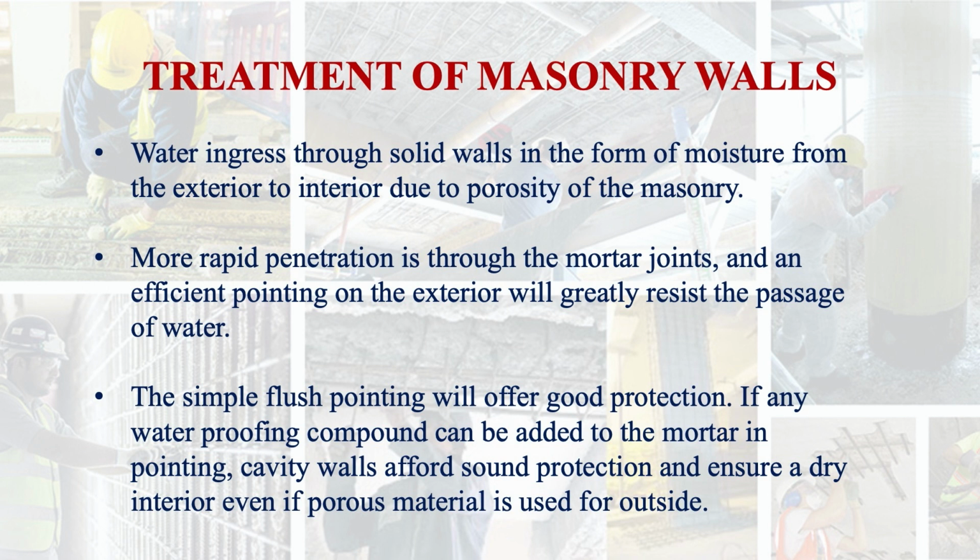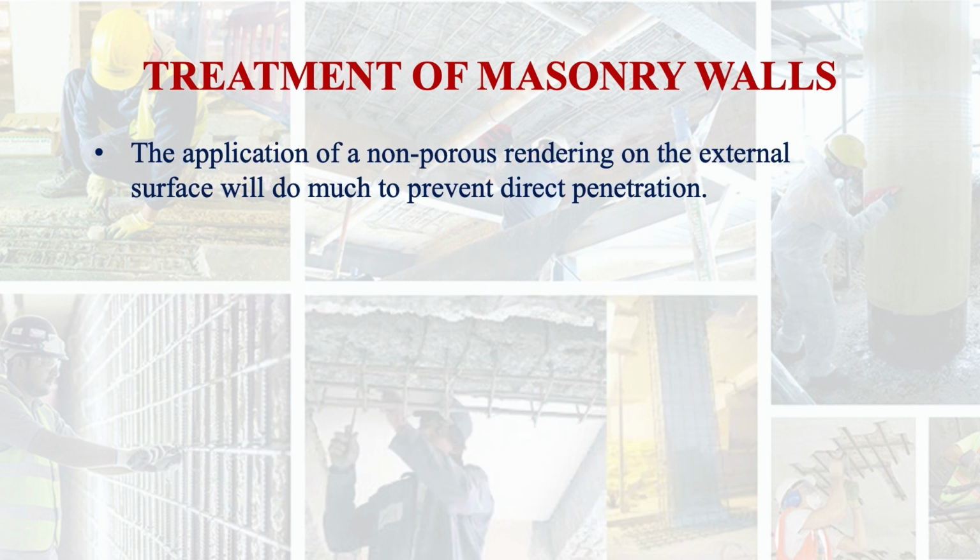If any waterproofing compound can be added to the mortar in pointing, cavity walls afford sound protection and ensure a dry interior even if porous material is used for outside. The application of a non-porous rendering on the external surface will do much to prevent direct penetration of moisture.